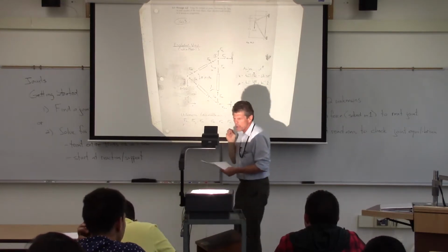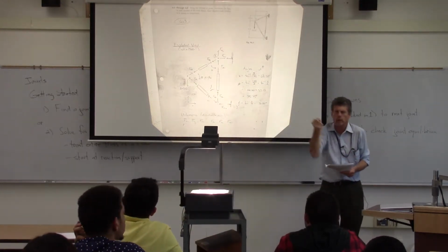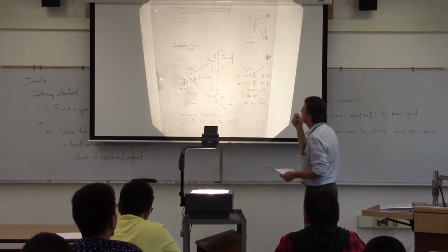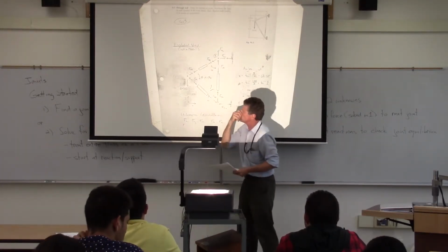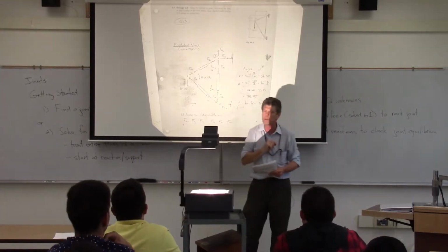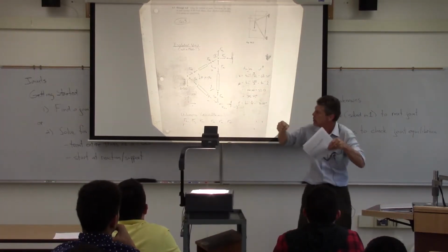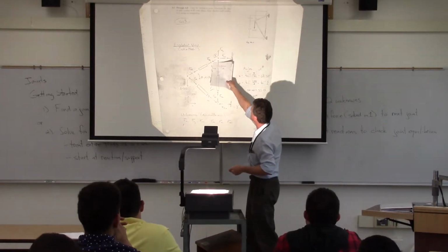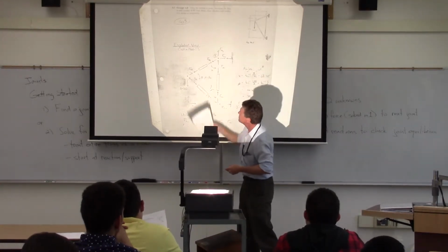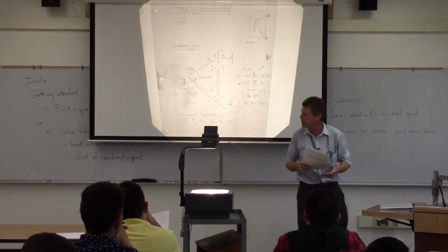So when we think about what it's doing to the joint there, it's going to be pulling away from the joint. And then equal, opposite, and collinear force there, the member force is going to be pulling on the member itself. So you can kind of see how the tension of a member relates to the tension of a joint there. It's pulling on a joint there, and it's also going to be pulling on the joint there at B.